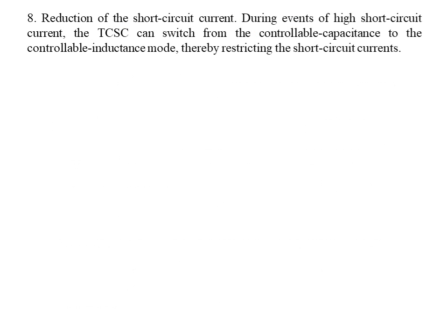And the last advantage is reduction of short circuit current. During an event of high short circuit current, TCSC can switch from controllable capacitance to controllable inductance mode, thereby restricting the short circuit currents. So this is one of the advantages of TCSC.